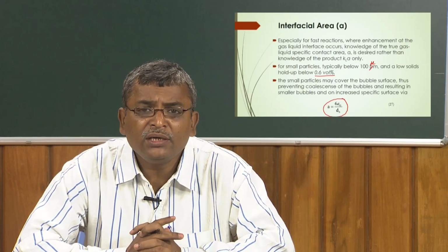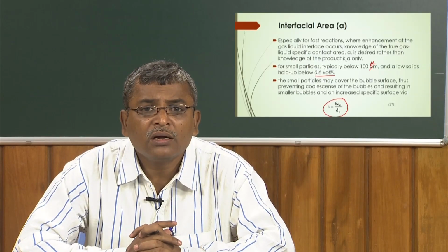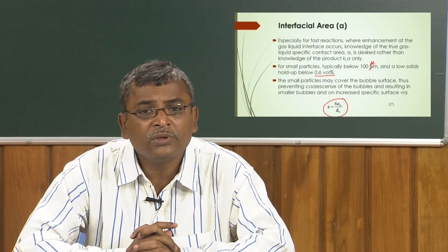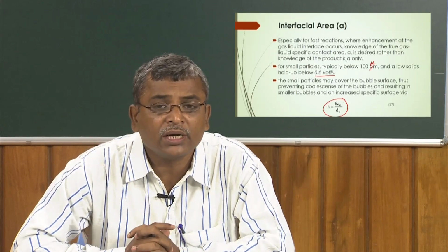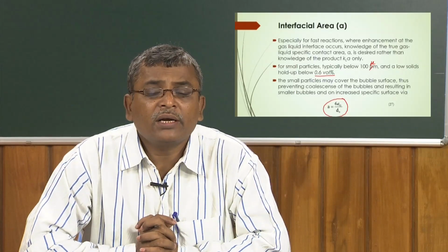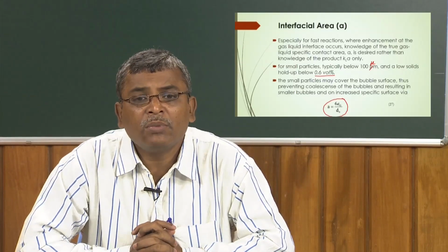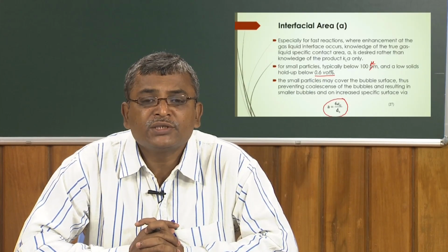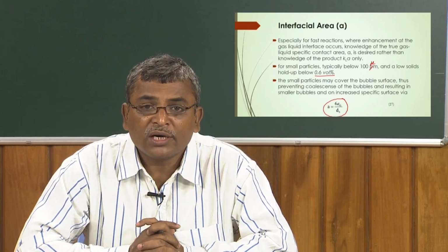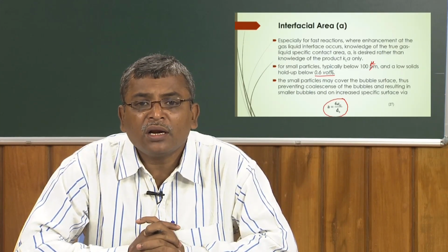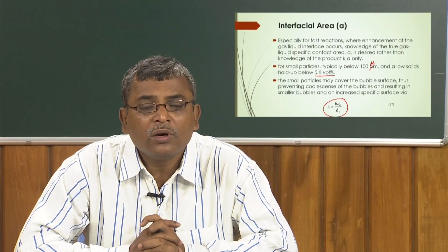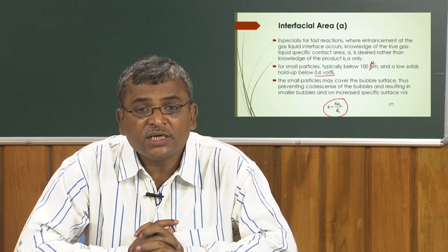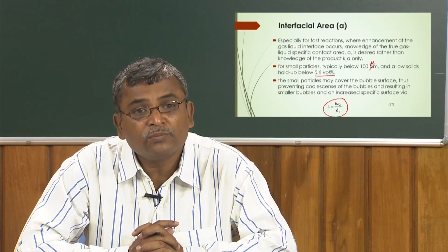Now, for this you need further information about the gas hold up inside the bed. How to estimate that gas hold up, we have already discussed earlier also: you can estimate this gas hold up by the phase isolation method, or by the conductivity method, and there are several other methods to find out the gas hold up. And I think the phase isolation method is very easy for calculating the overall gas hold up.